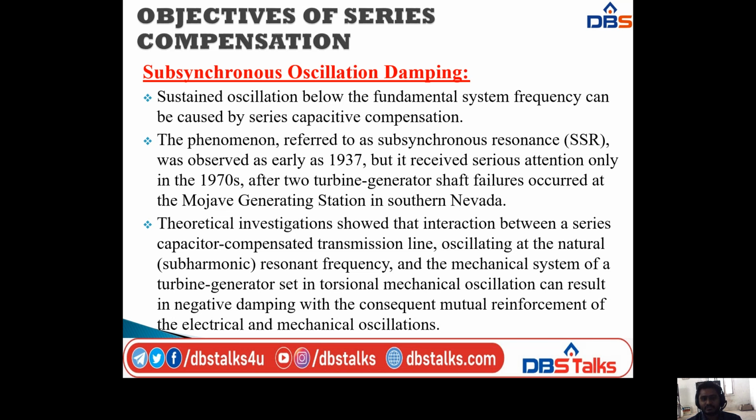Theoretical investigation showed that interaction between a series capacitor compensated transmission line oscillating at the natural resonance frequency, that is a subharmonic frequency, and the mechanical system of a turbine generator set in torsional mechanical oscillation can result in negative damping, with the consequent mutual reinforcement of the electrical and mechanical oscillations.